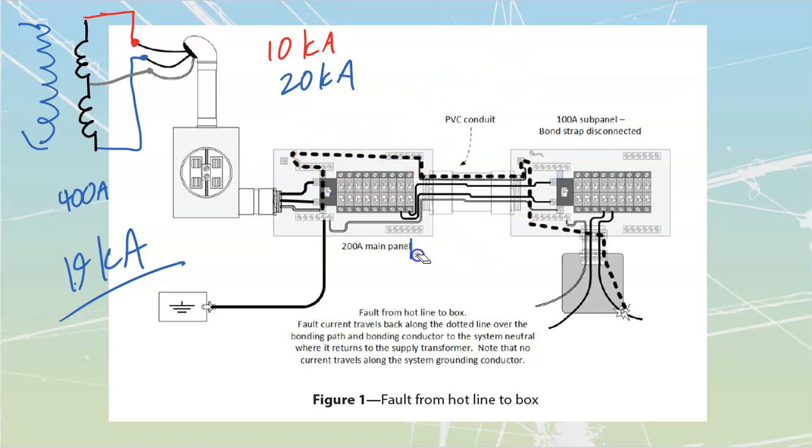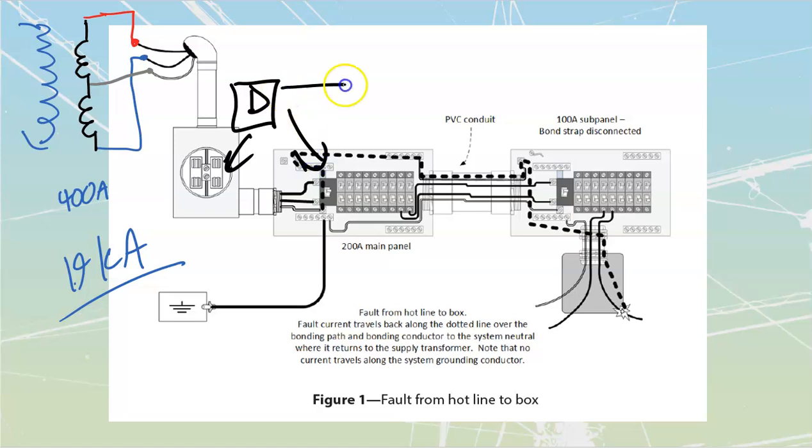In a lot of cases, if you, once again, stick with a manufacturer's entire product line, if I'm dealing with something and it's all going to be Square D over here, then this, in a lot of cases, is already going to come pre-series rated for me. But you have to be careful. As soon as you start fooling around with changing different types of panels and breakers and suppliers, there's always that chance that that series rating is no longer going to work out.